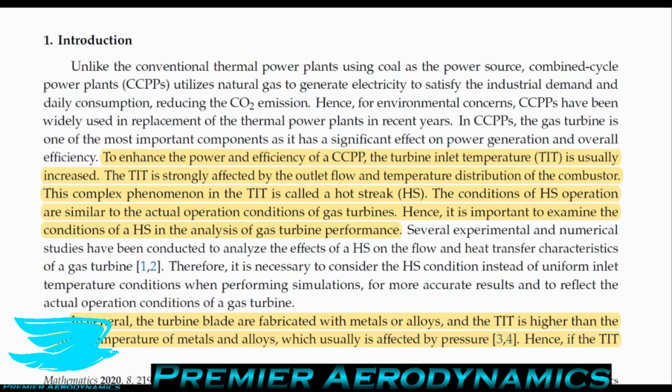So if you treat the gas, for example, as an ideal gas, that's the easiest way to do it. You then can look up the enthalpy values of the ideal gas or calculate them very easily. The enthalpy is a measure of how much energy the gas has at a certain temperature. And so if you understand what the enthalpy is at the start compared to at the end, you can determine how much energy has been extracted. And then you can figure out how efficient this turbine is operating. So the higher that difference, the better the turbine is operating, generally speaking.